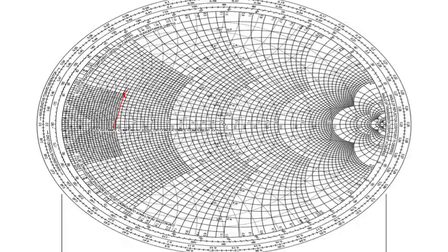If you remember, this was the ZS point. This was the ZL point, 0.2 plus j 0.2. And now we are going to move downward. When we are moving towards downwards, it is always represented by a capacitor. And since we are moving along the solid circle, can you all see this? Solid circle, it's a solid circle, not a dotted one.